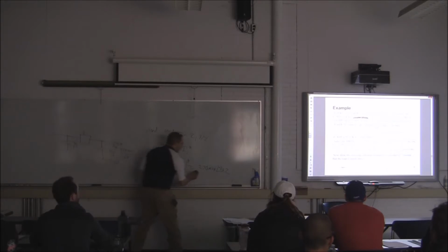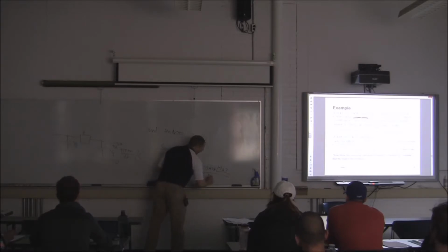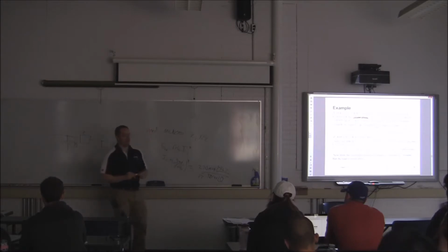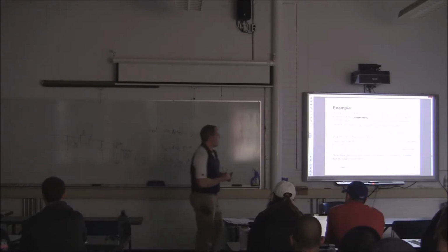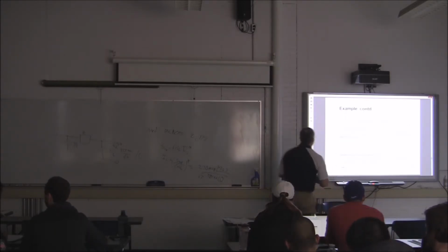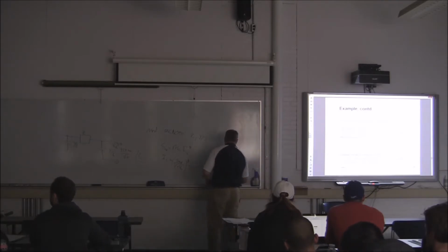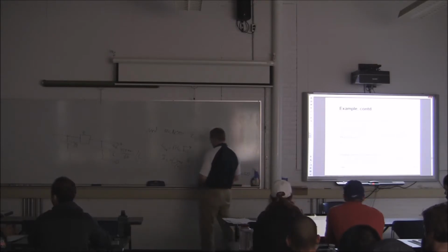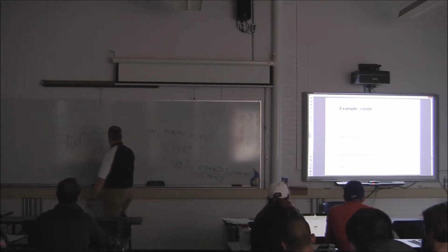So then I divide by the square root of 3 times 325 kV, and I take the conjugate of 0, which means it is 0. And the current that I calculate is, let's just be lazy, 480 at an angle of minus 36.87. That is what I R is.